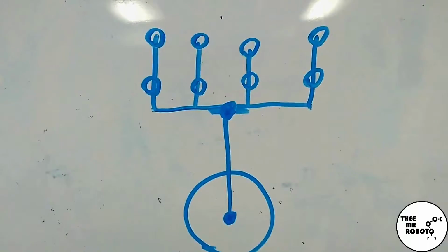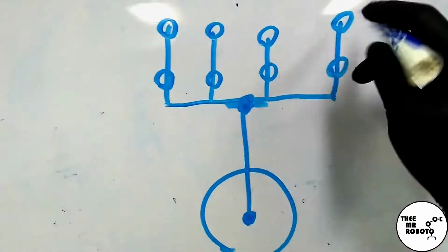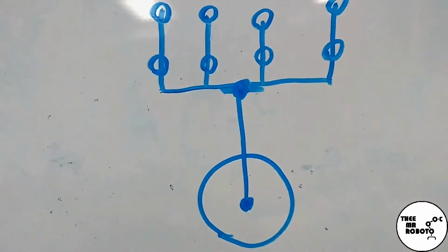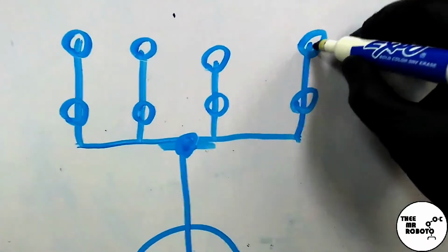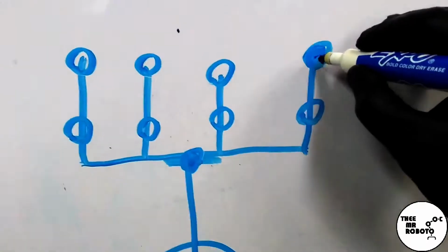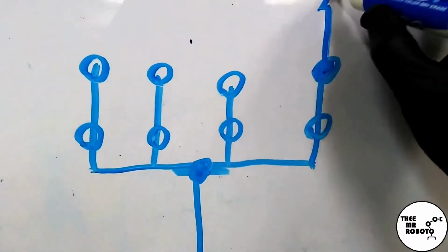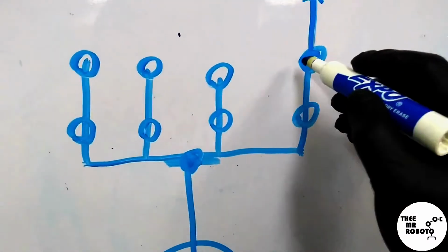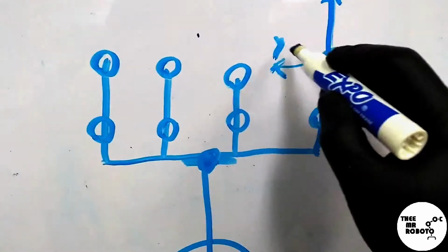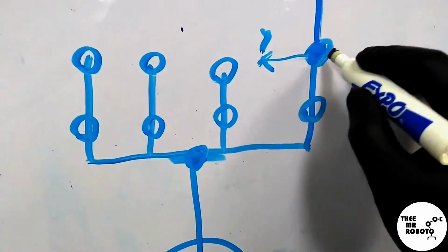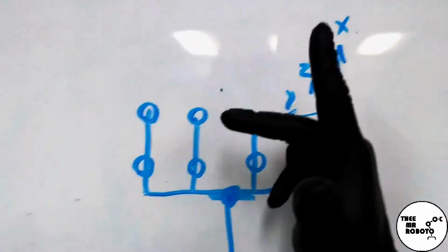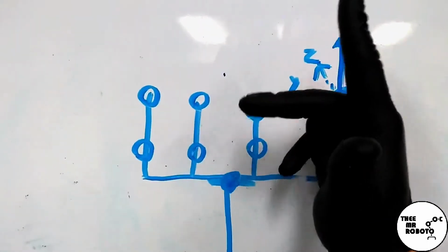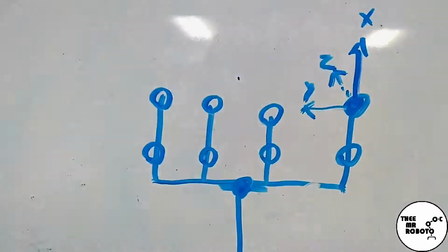Sometimes it's good to have a coordinate system that's based on the shape of your end of arm tool. Okay, so for instance, let's say that I set up a coordinate system here, right? We're going to say this is the X, this is the Y, and then sort of coming up at an angle, that's the Z, okay? So think of it like this, all right, with Z here, X here, Y here, okay?